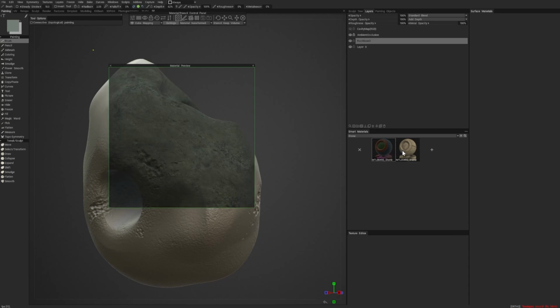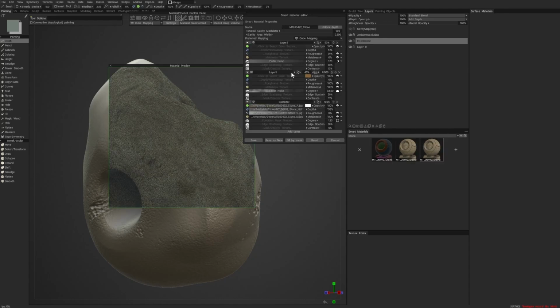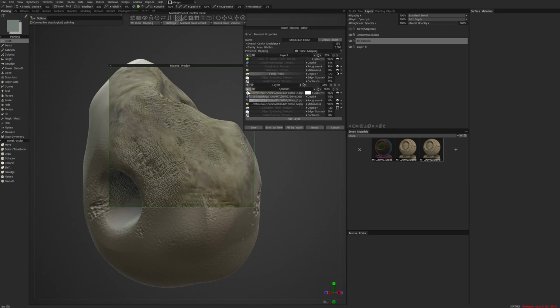I've set this material, and I've made a variant of this. So if I right click on that stone material and I go to Smart Material Editor, or if I go to Duplicate, and I go to the duplicate and I go to Smart Material Editor on that, it has a material that it automatically wants to set, but I can go into that material and there's this base layer. So you can kind of picture this as multiple layers.